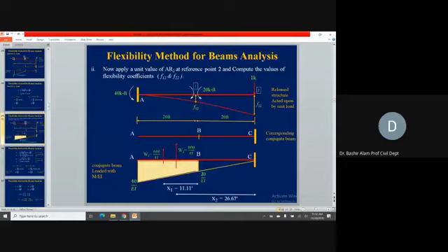The conjugate beam loaded with the M over EI diagram. Now this hatched portion is showing you that when you are taking now the moment about B, only this hatched portion will be included. And its weight or its area is becoming 600 over EI. This is when we take the moment about B. But when we take the moment about C, then this whole triangular portion will be included, and its area, which in turn is its weight, W2, it is becoming 800 divided by EI.